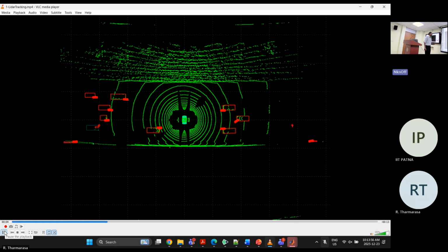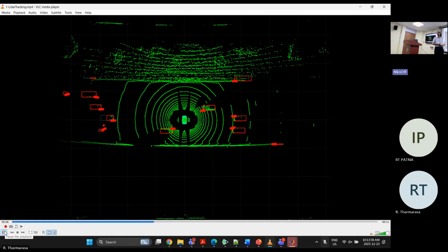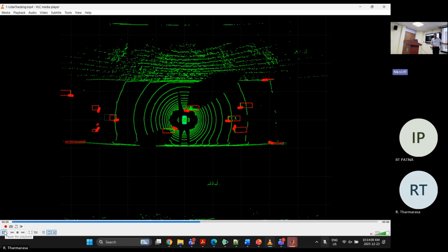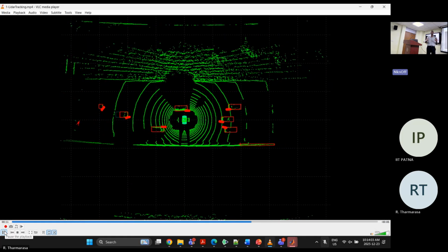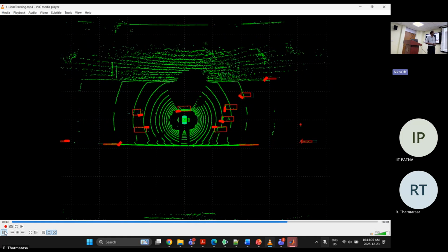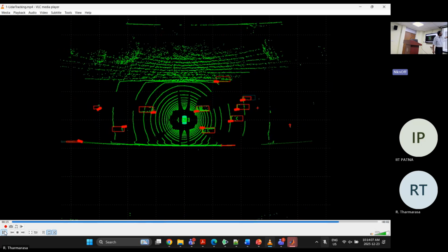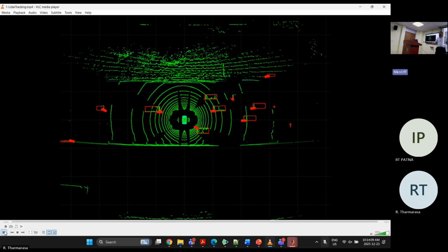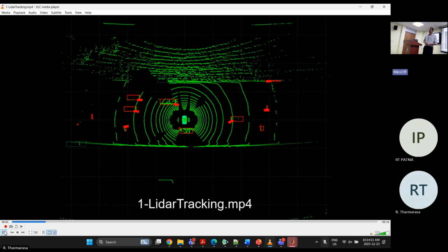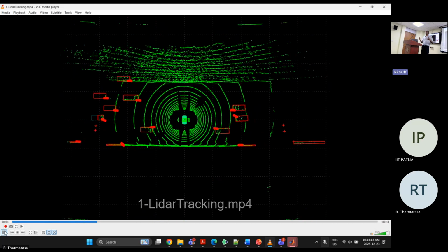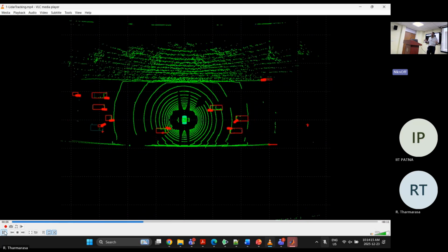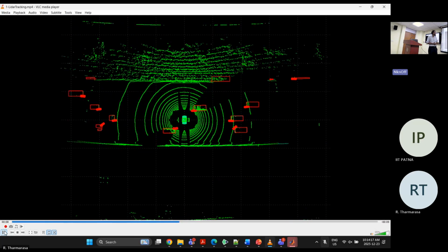So if you look at this, this is actual real data from a self-driving car. So this is LiDAR. If it's a radar, it's similar but with less dense data. Okay. So in this case, the green dots are the detections, or we call them measurements, from which we want to extract tracks. That is our objective. Okay. So the objective is to identify the car, right?